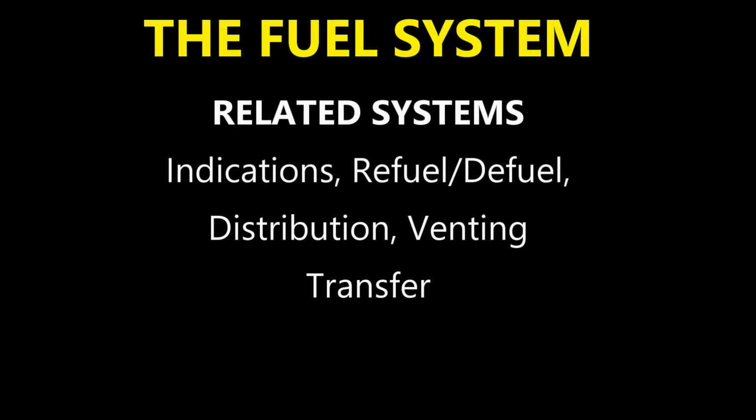Okay, now distribution of fuel. That was recirculation for the cooling of the oil for the IDGs. We use recirculation pipes, and we have the pressure holding valve so that we don't have too much pressure in the recirculation pipes. Now we're talking about distribution, because we want to get that fuel to the engines, right?